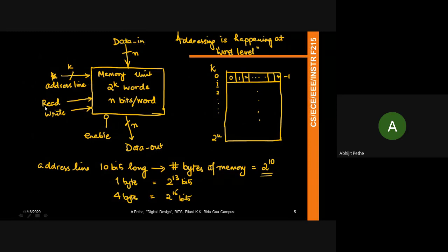So these signals become very critical, and these are timing sensitive signals. So this is where, when we discuss timing diagrams, when we discuss timings, those become important. That is, you essentially want to always ensure that the write is a pulse. Write should never be enabled and left as is, right? Write should always be a pulse, and the pulse width will be determined by the worst or the longest time taken for data to be written into the memory.